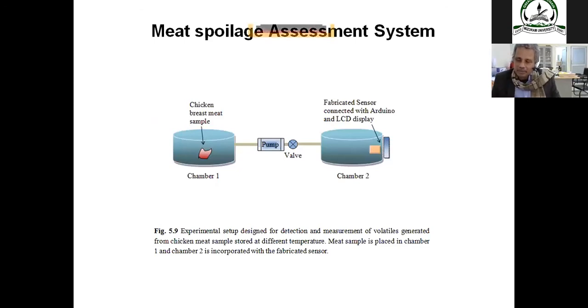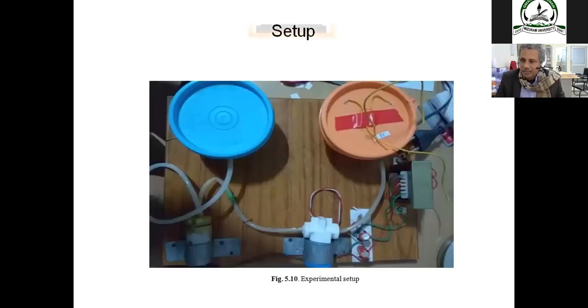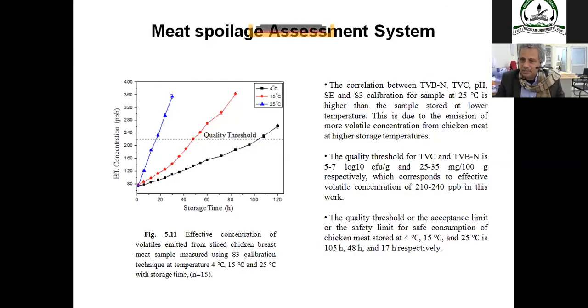This is a measurement setup. You put the samples inside a chamber, and the gases are put in the chamber through a pump and come out through a valve. We control the amount of gases; the valve and MFC will change the concentration of gases. This is our setup in our laboratory. We have made it; this is a picture of the setup, for mid-spot and calibrated measurement.